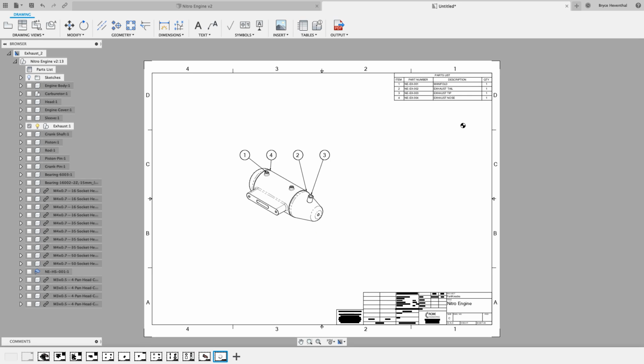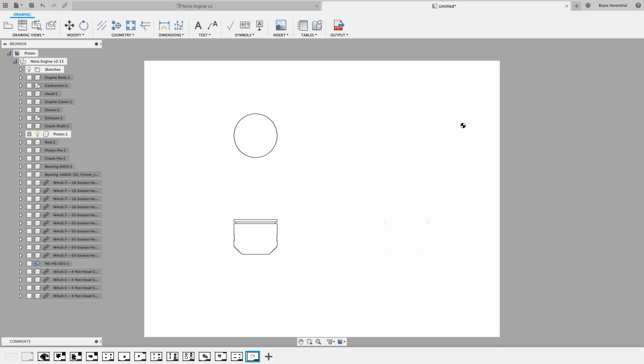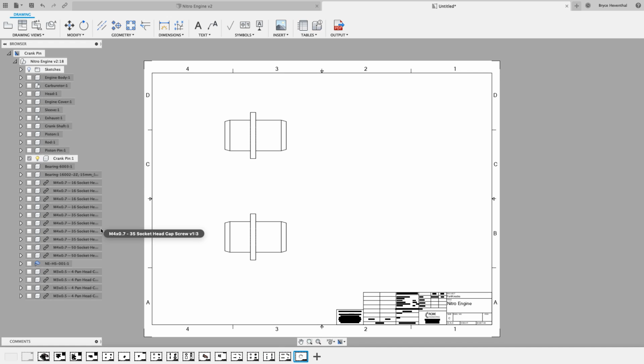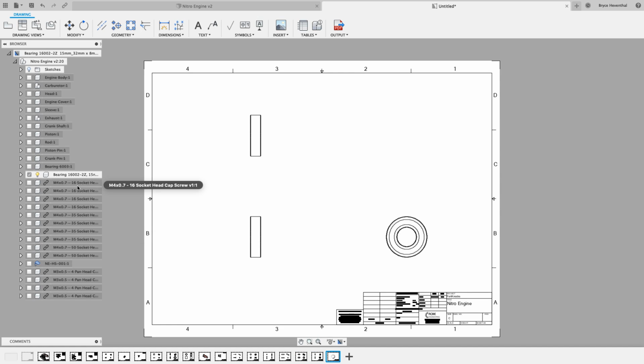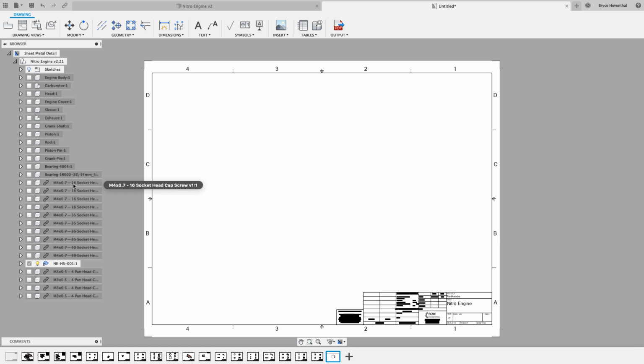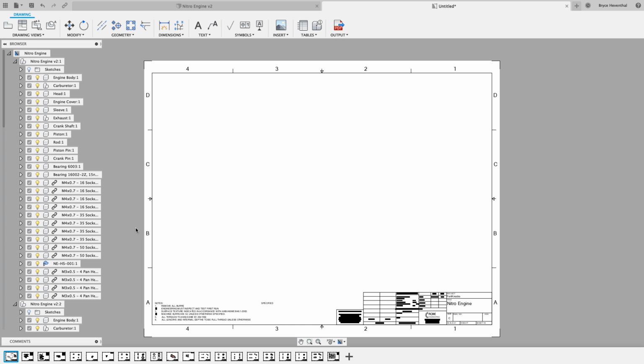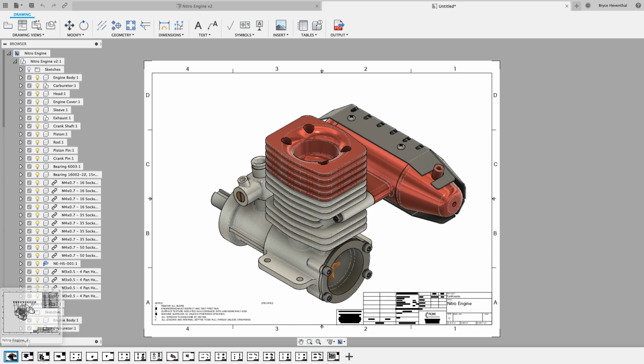So you'll see that it goes through, it's just pumping through my tree, and you'll see one by one it steps down, steps down. It already made a couple of my exploded views from those animation workspaces as well. You'll see it skips those linked components, and that's because I unchecked that box when I started to make it. And voila, it's done. You see I actually just quickly made about, I don't know, 13 to 15 drawings. You can always come and rename the sheets afterwards, or print output a PDF for one sheet as well.